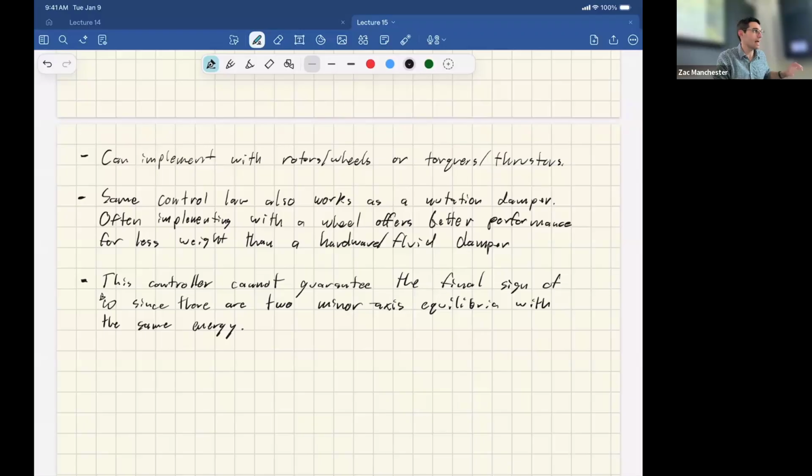Okay. Last thing for the day. So we got some Jacobians for thrusters and wheels. These B's that we just wrote down are constants that are fixed based on the spacecraft design, right? So you choose an array of actuators, and then that sets up what this B matrix looks like. We haven't talked about CMGs. Those are trickier.